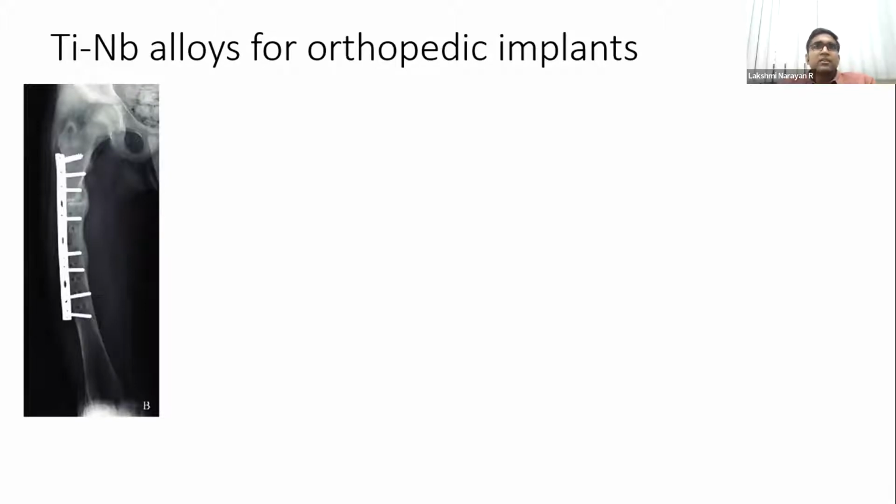And for an implant, if you have the stiffness of bone, which is given as 3 to 25 GPa, one would expect that the implant stiffness should be similar, right? Because you're going to go with something which has got the same stiffness. But there is another school of thought that would say that I want a stiffer implant, because let us say there is a problem that I put excess pressure. I don't want my fracture to become exacerbated, right? I don't want it to become worse.